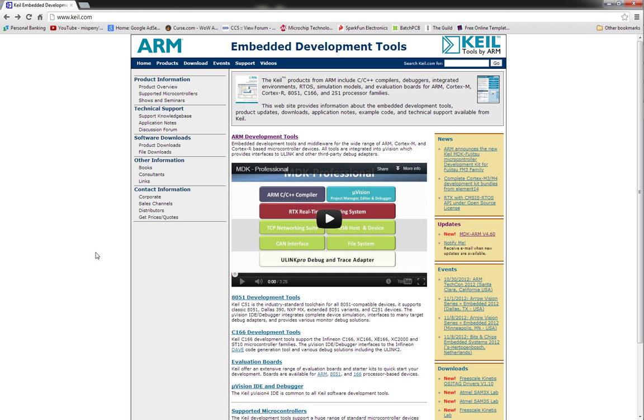And it's a full IDE, whereas in later videos, once I get them figured out, I have to admit that it's pretty complex to get the linker scripts and things written properly for the GNU versions. Once you get that put together, you can use other IDEs like Eclipse or NetBeans and couple the tool chains with that, and basically gain the integrated development environment you need to start building full-fledged embedded systems and images for the ARM processor that we're going to be dealing with. So maybe in later videos I'll get the GNU going.